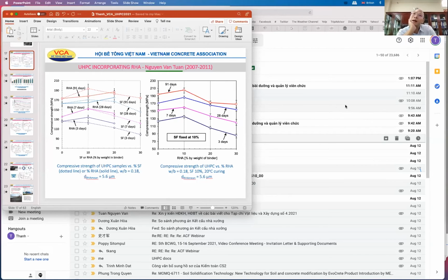I have Professor Kang. Yes. We have the associate professor and Dr. Nguyễn Văn Tuấn. He did a lot of research with rice husk ash UHPC, and in the chat box, Tuấn would like to comment and exchange his view on UHPC using rice husk ash. Okay, all right, so please. Tuấn, can you say something about UHPC rice husk ash? Okay. Yeah. So the rice husk was burned, uncontrolled, at a temperature from 700 to 800 Celsius degrees.